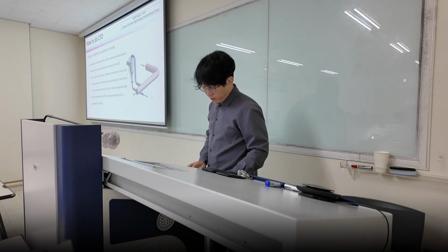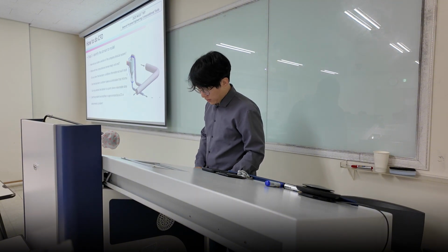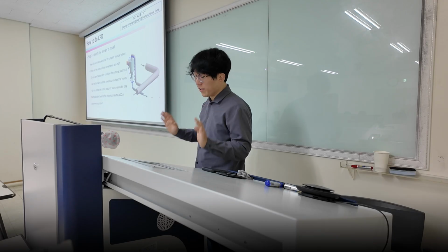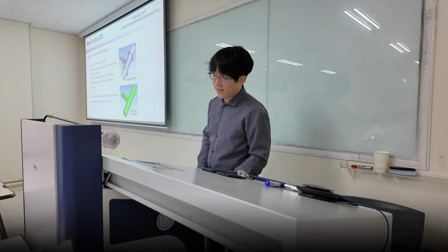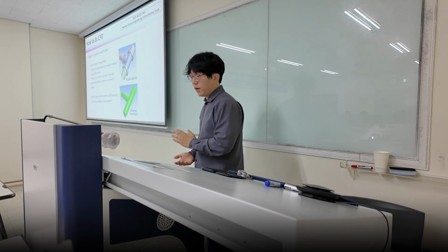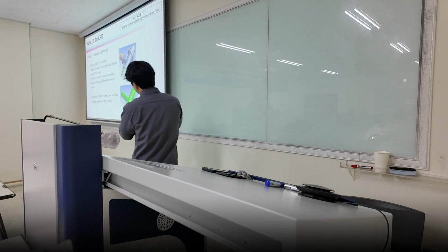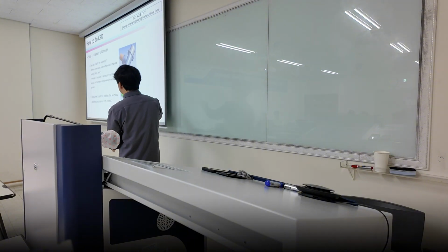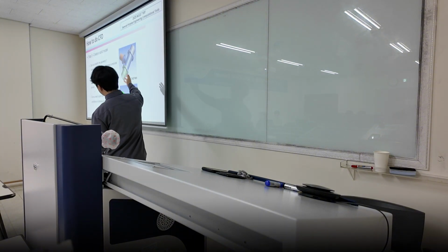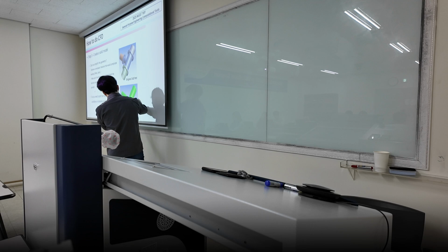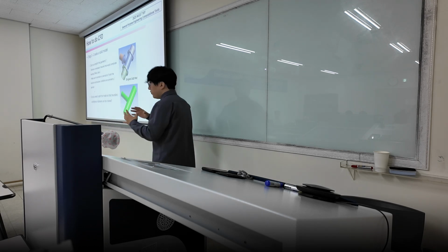So these are really, really important because I've been working on computational fluid dynamics for a long time, and I just wanted to explain this once and not bother you again. And then you have to create a solid model. What you can see here is the actual solid model seems pretty unnecessarily complicated, but you can extract out the inner fluid domain, and then it can be very, very simple. You can simplify.